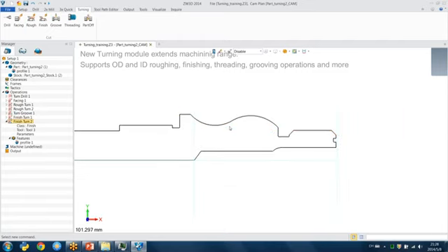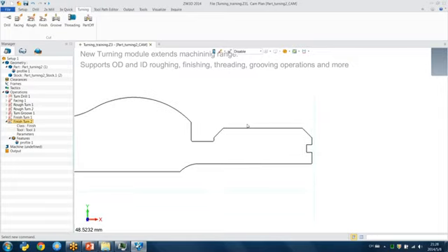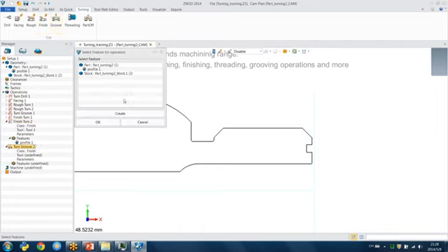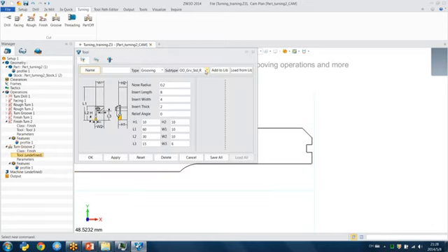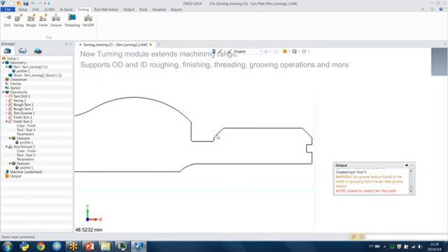After the finish operation, the last operation, I need to do the grooving on this side. So I need to use the grooving profile, the same profile. Tools, I need to choose. You can find type, facing grooving. You need to choose right facing grooving. You can find the first will change to cut the side. So I use the default one. Press OK and calculate. Unable to correct the toolpath.